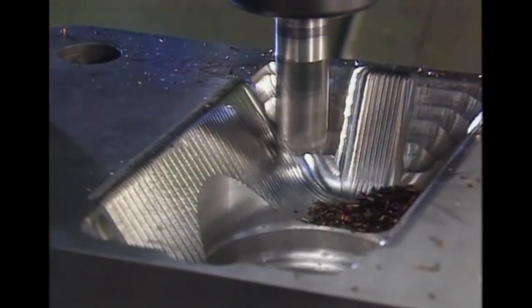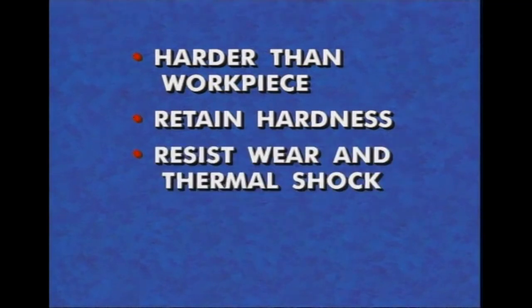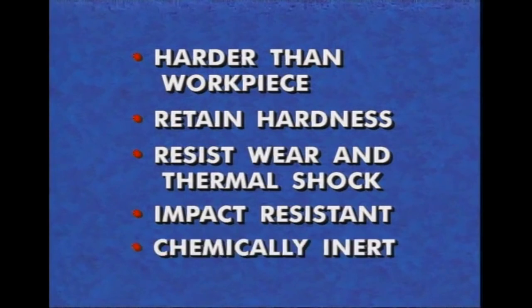For the wide variety of machining applications, there is a corresponding necessity for different cutting tool materials. The ideal cutting tool material should be harder than the workpiece it is cutting, be able to retain its hardness and stability at high temperatures, resist wear and thermal shock, be impact resistant to withstand the mechanical shocks of milling, and also be chemically inert to the work material and the cutting fluid.